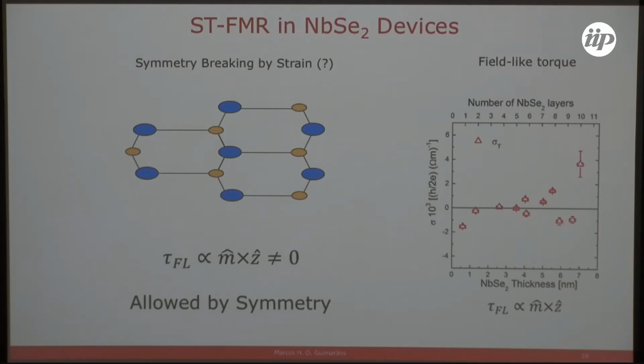The problem is we can't control anything in this. So what I can tell you is that for the same fabrication run, you have many points here which lie sometimes negative, sometimes 0, sometimes positive. They are different flakes, and we have to go through a very complicated sample fabrication process. So the strain from device to device can very well be different. It can be in different directions. It can be compressive or it cannot be there. So it's difficult.